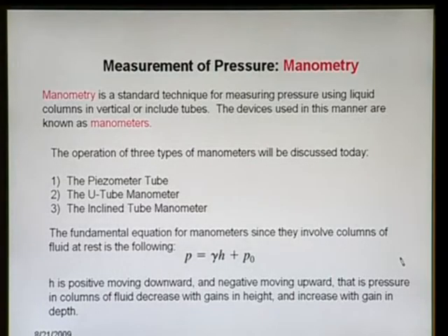By understanding the pressure equation we came to know that in a static fluid pressure does not vary in the x y plane, or we can say in the horizontal plane. Pressure is a function of the weight density only, and it varies only in the z direction, and dP over dz is equal to minus gamma. It means pressure decreases as we go upward, and pressure increases as we go downward, right.